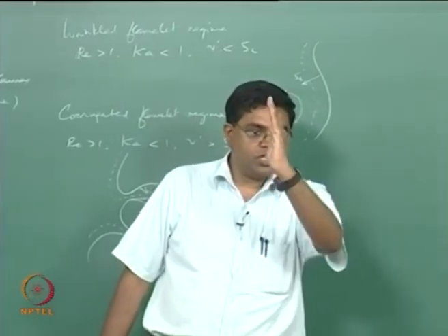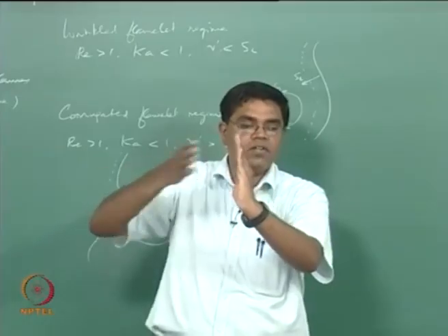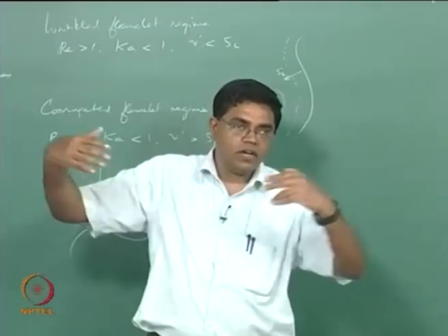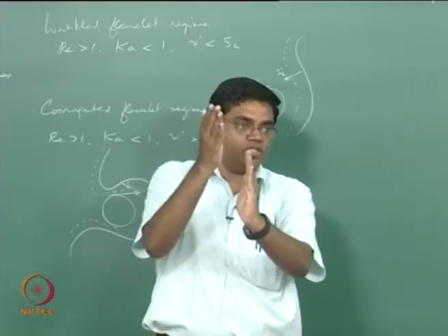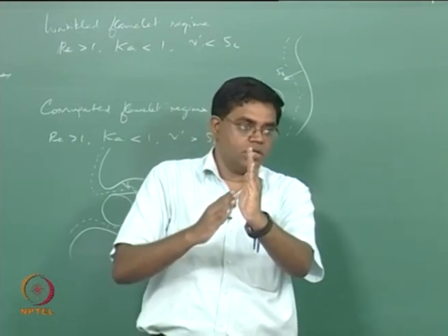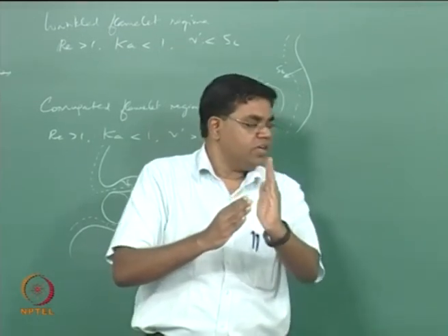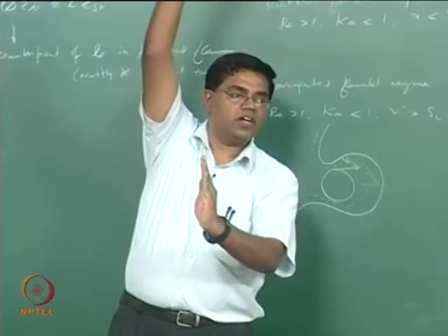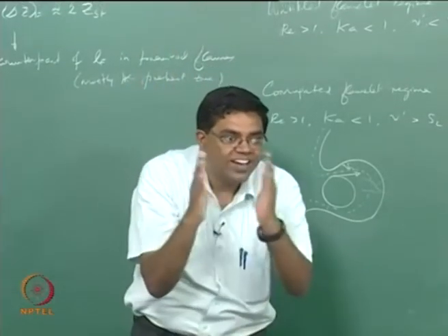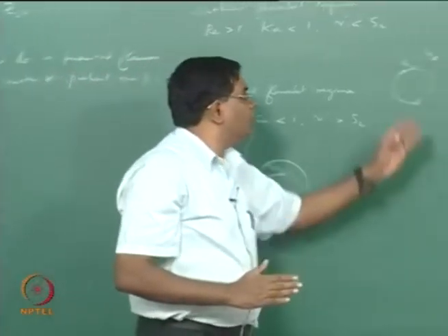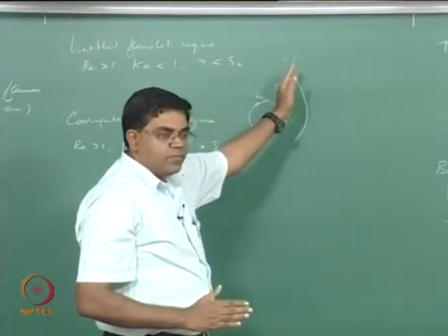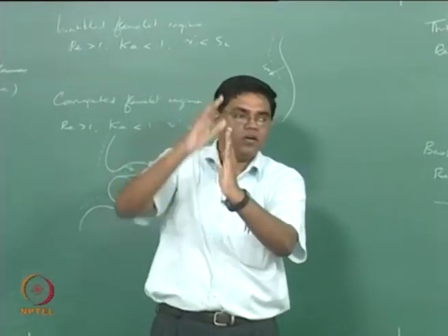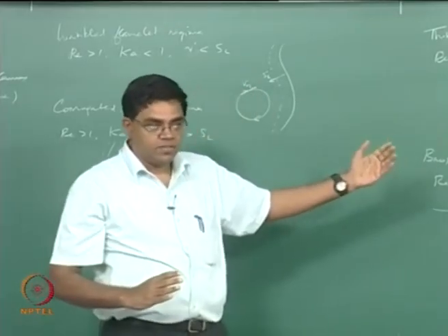You have a flame that is a sheet which is like a reaction zone, and you do have the transport going on, that is mixing of fuel, oxidizer and heat. All these things are going on outside of this sheet, and if you want to think about what happens to the reaction rate, the infinite reaction rate assumption is the one that says that the reaction rate is almost infinite here. But if you now try to zoom in and clarify this reaction zone like we would do in the premix flame, then we would find that it's essentially the reaction rate that is going to be peaking only at this sheet, similar to how we did in premix flames, right.